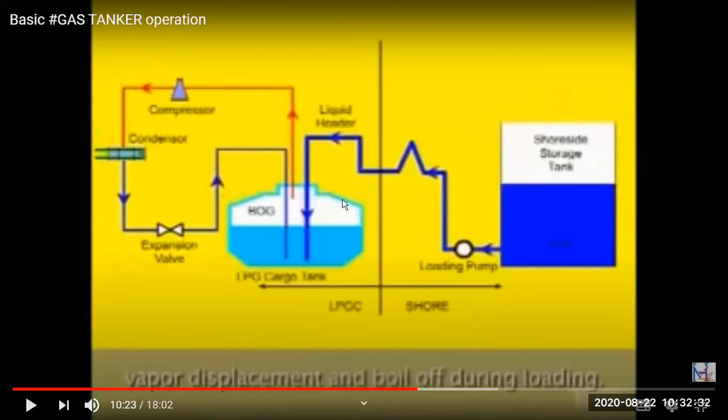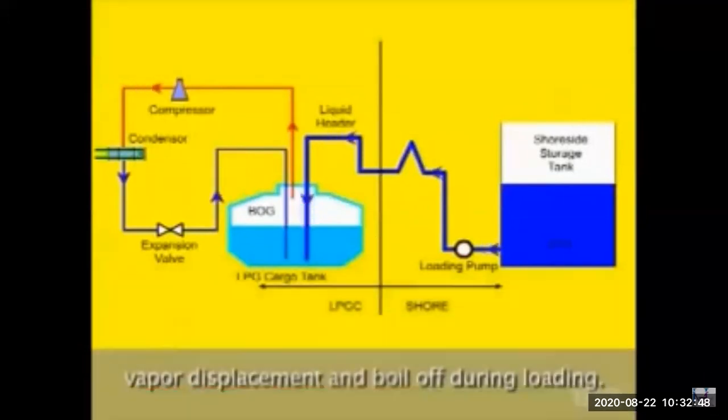Otherwise, with the exchange of heat, even if you have insulation, this insulation is not 100%, and slowly, over a long period of time, all the liquid will become gas if we don't have a reliquefaction plant. Vapor displacement and boil off during loading.